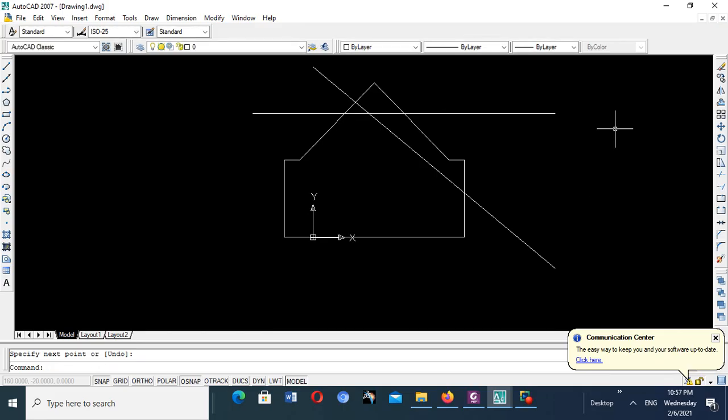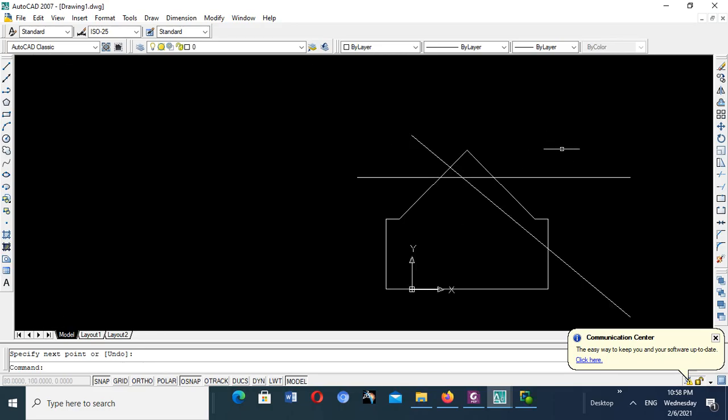So I want to teach you the trim command, how it works. So let us say I want to trim this. You see, let us say this is my boundary for the trimming. So this upper part of this inclined line I want to trim off. This upper part also I want to trim off, and also this line I want to trim off, so that I just remain. When I come from that side, I go to that juncture and I go straight this way and I go down. That I want to remove by the modification called trim.